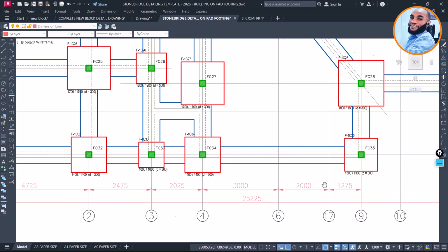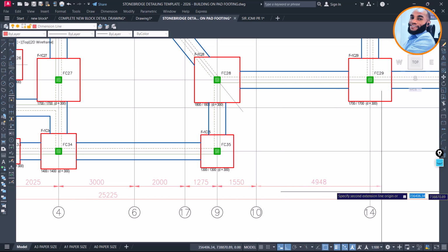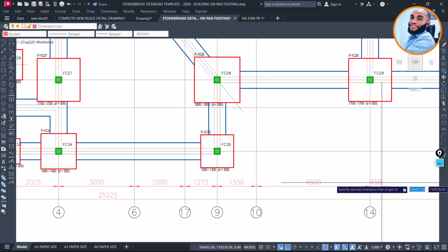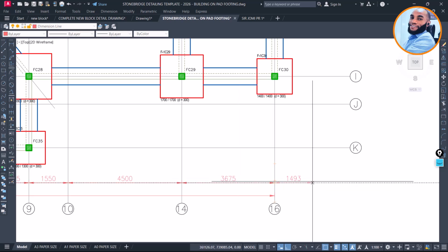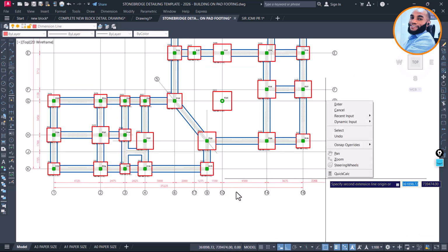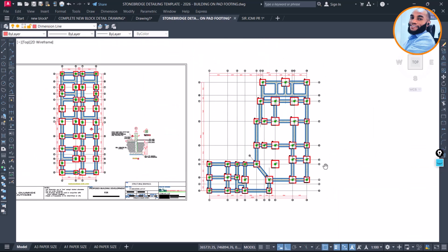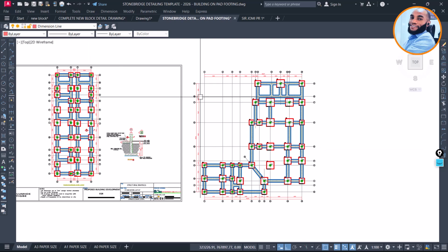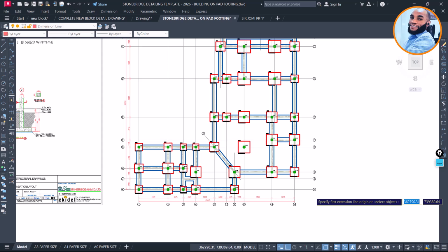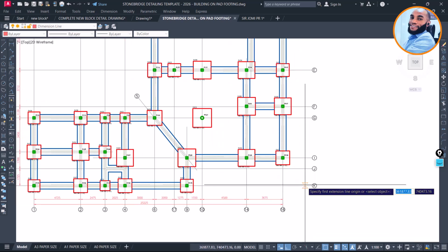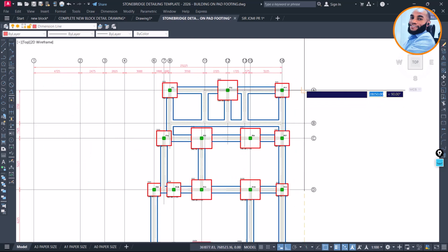and again this other one here. So make sure you carefully do that so you don't make a mistake, and then click on this. Okay, that's fine. And again I press the escape key, and then this last one now here, I'll type again DIMLIN, enter, and then I'll come here, click on this, and I'll go up here and then click on this here.